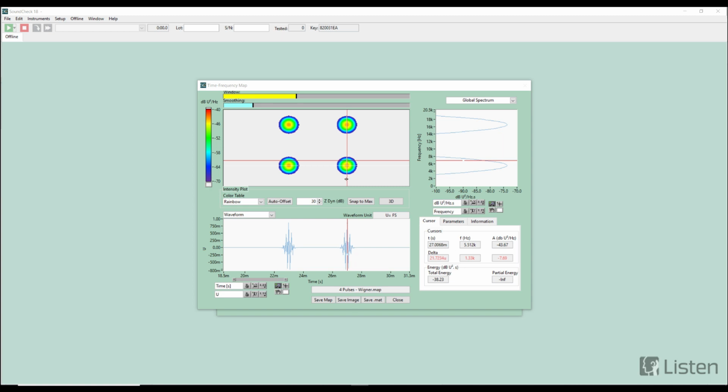On the right of the spectrum graph, we have the frequency display. This is transposed from the typical format of how we view frequency and level. The reason this is done is so that the frequency axis corresponds to the layout of the power spectrum graph. With this display, there are many different selections that we can make for looking at different portions of the spectra and the waveform.